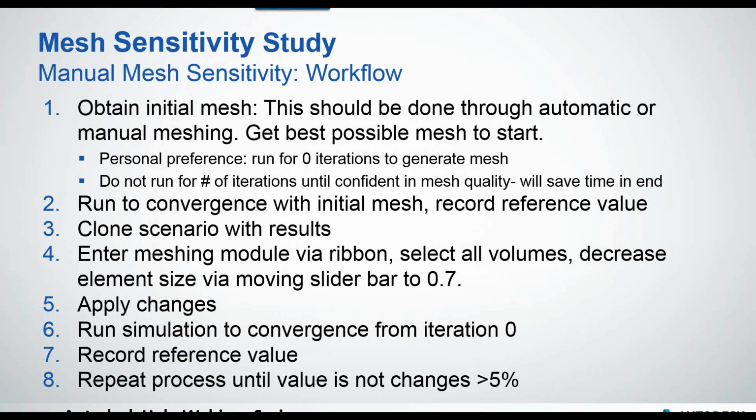And I wish more people would focus on this. I should have bolded it. Don't even bother running for any iterations, to convergence or whatever, until you're confident in the mesh quality. It's really like step 1 or step 0. If that's not good, then everything else is a waste of time.